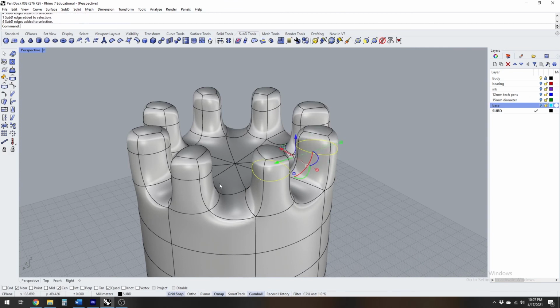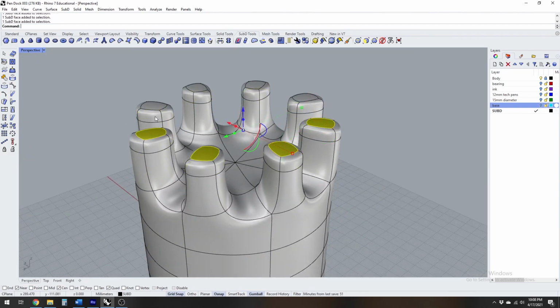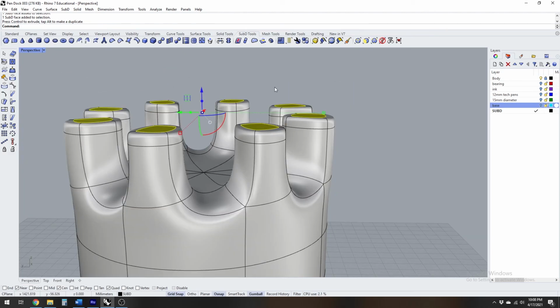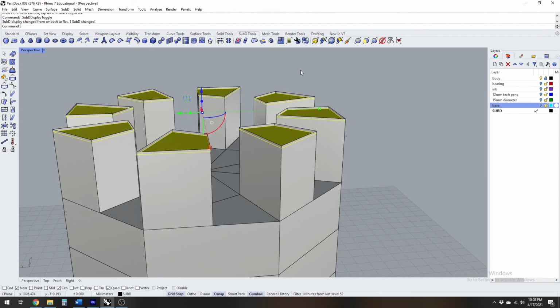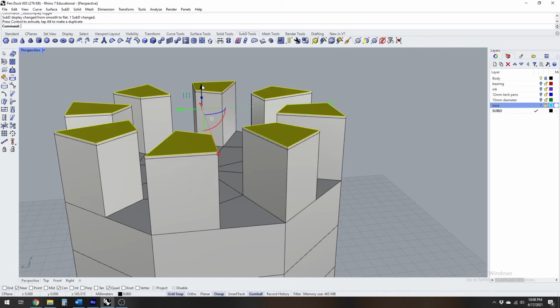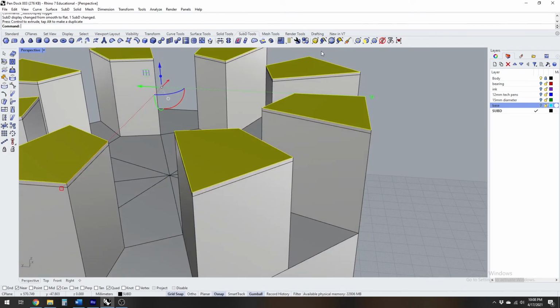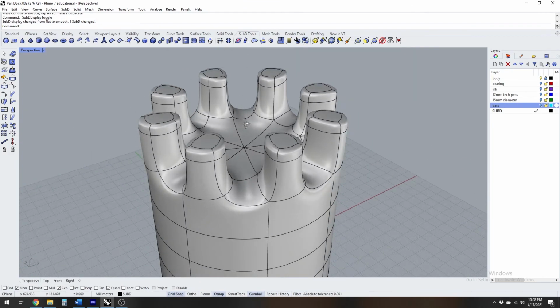All right, here we go. We're going to do all of these selections, and then by shifting them closer to each other, we establish something that's more traditionally associated with a filleted edge. Now, I did make a little mistake here. I don't want to tuck that geometry in. I always want to keep it as normal as possible, and that will keep us from possibly tearing our surface at the end. And it is going to be a 3D printable surface, so I don't want to push it too hard.